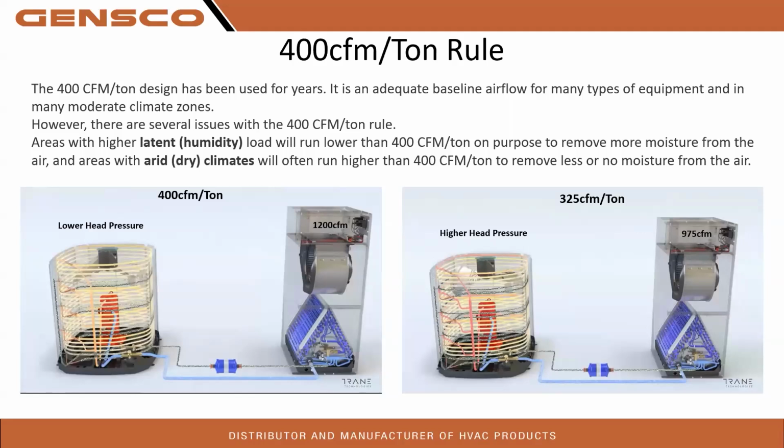Because as we know, whether it's heating or cooling, our sensible delta T, our dry bulb delta T, if we decrease airflow, we increase our delta T, our sensible dry bulb readings. We've all seen it. If you haven't seen it, give it a test. Change your airflow. You're going to see delta T increase. And the math after the equal sign will not change too much when we are increasing or decreasing airflow. But we have to keep all these things in mind when we're charging equipment.